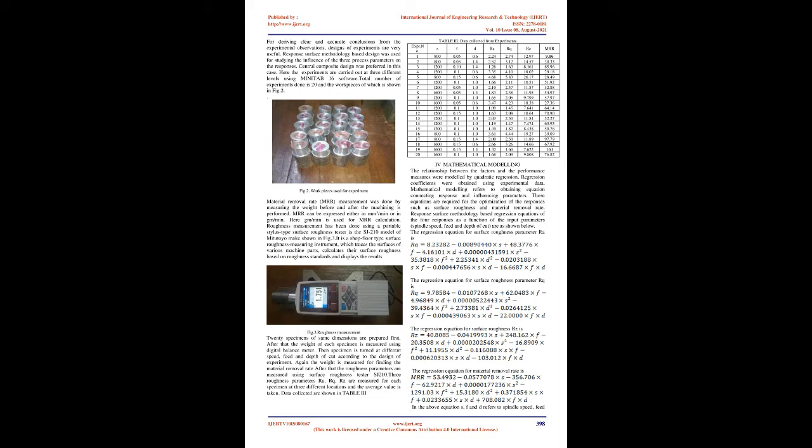Analysis showed that surface roughness and cutting force were significantly influenced by feed rate, whereas the tool wear was significantly influenced by cutting speed. 3 levels and 3 factors design were used for experimentation. Rajesh Kumar Bhushan [15] analyzed and carried out optimization of alloy SiC composites for minimum tool wear and maximum material removal rate using tungsten carbide tool.